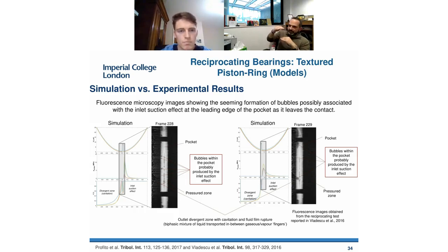Whilst if you're already in the hydrodynamic regime, increasing the amount of film could sometimes bring back more viscous losses, as you're adding more fluid that you need to shear. And this could be verified: the inlet suction, even in this condition, the one that we see in the videos from the movie I showed you before, seems to correspond to the exact situation that we model in our system when we put the full mixed elastohydrodynamic lubrication together.